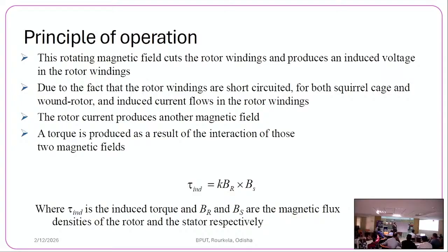So that way torque is produced, and that torque makes the rotor rotate. Why does it rotate? Because another law is there. Electrical engineers, all of you know Lenz's law. It tells us that wherever electromagnetic induction is there, and I am not stating it, I am explaining, the nature of the electromagnetic induction is such that it opposes the cause that produces it. Okay, the nature of the polarity.